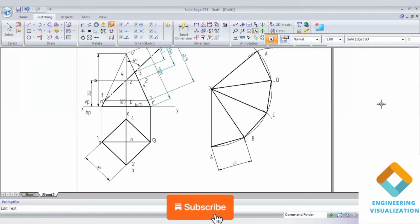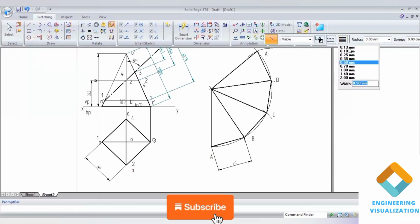Now the cut points, we should mention the dimensions which I have already measured on the slant edge. Okay, A1 the same length arc we should cut. Similarly for 2 and 4 it will be the same length, and for 3 it is the length which we measured. Okay, go to arc by center and type that same radius for